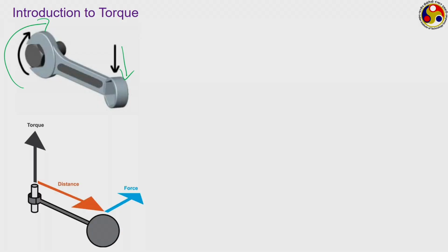So, this is the way we can calculate the direction of torque. Quite often we can relate this to a left hand thumb rule kind of situation, quite similar to what we do in electricals. If we place these three fingers of your left arm perpendicular to each other, then if the index finger gives you the direction of the force and the middle finger gives you the direction of the distance, then the thumb is going to give you the direction of the torque. Or sometimes we can also relate them by something like this: if your force is acting in this direction, then depending on whatever way you are looking at the force, or if you are standing at the point with respect to which you want to measure the torque, whether you are looking in clockwise or anti-clockwise direction to find the force, accordingly we can also decide the direction of the torque.